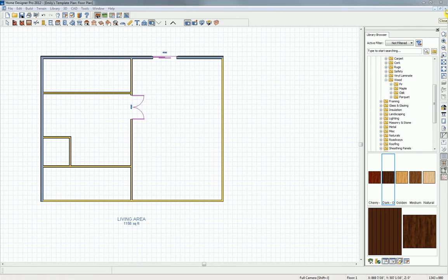So let's continue working with our doors in this view. So back to our door tool, I'll use that hinge door. And when you place a door, you can single click and just simply place it, and it will drop right in there for you. And then you can select it and use your rotation tool to rotate the swing side, hinge side, whatever you'd like.